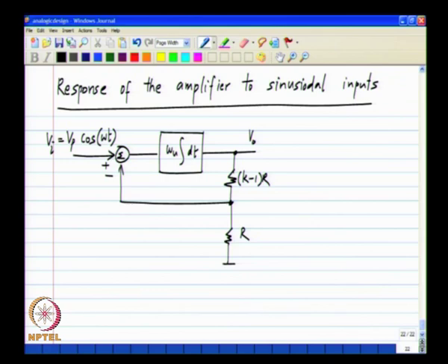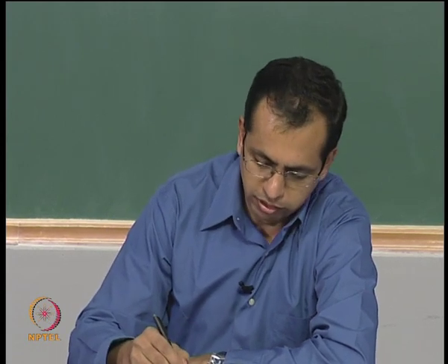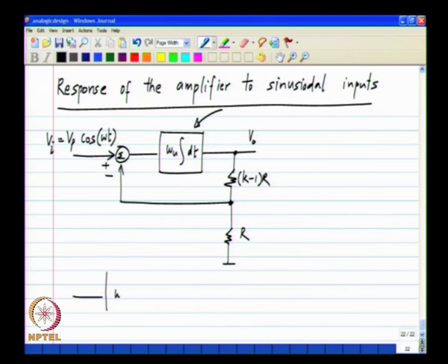Now, as you know, this is very convenient to analyze not in the time domain, but in the Laplace domain, where we replace the integrator with its Laplace transform equivalent. So, what is an integrator in the time domain is the same as this algebraic operation in the Laplace domain, that is omega u integral of time is the same as omega u by s, is the same as multiplying the input by omega u by s. Okay.